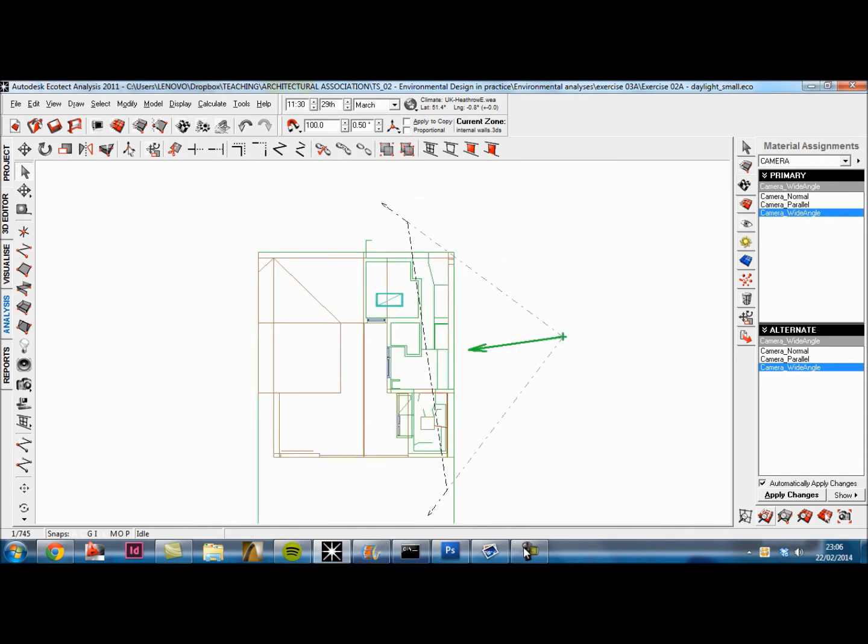And what I see in my field of vision is this line here. That is a line which Ecotect's or Radiance is going to clip its image for that line. This is a really handy tool because it allows us basically to see inside of buildings and cut sections. So I'm just going to move it just so that it cuts inside that room, still picks up that room there, picks up that, and then cuts through that roof right at the end. And once I can see it in plan, I know it's going to happen